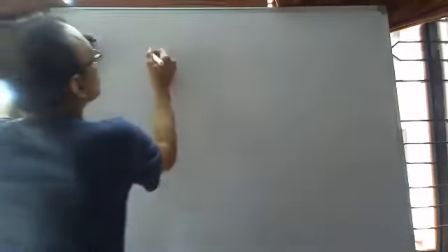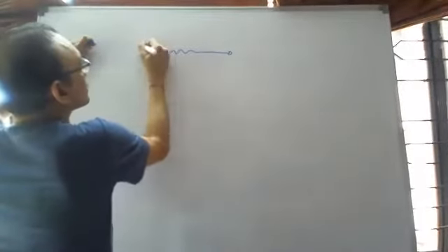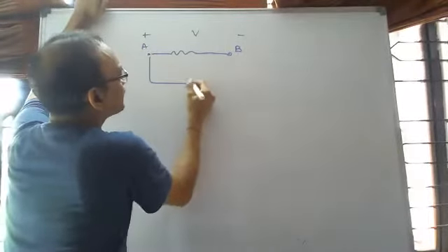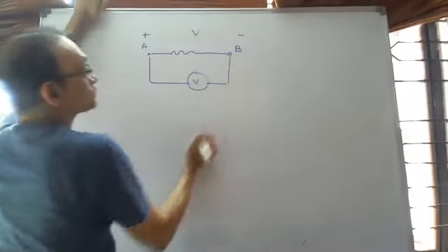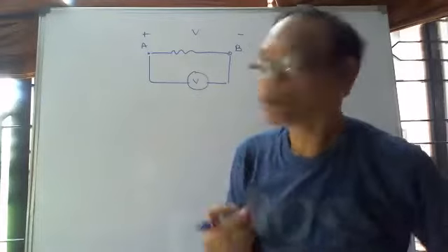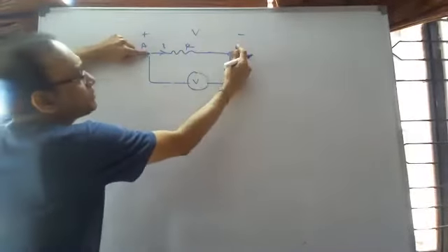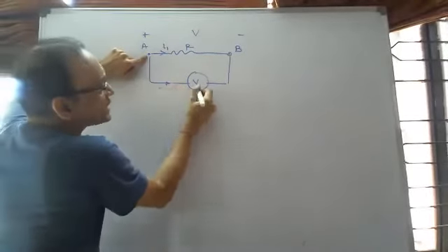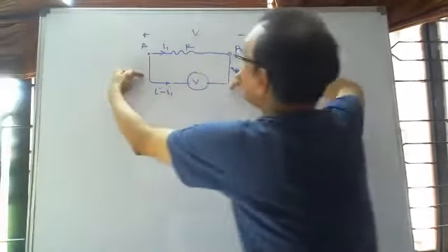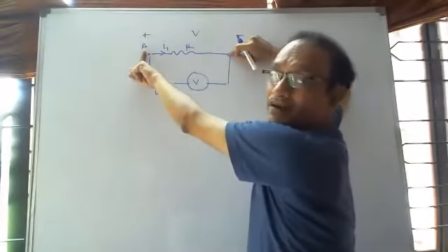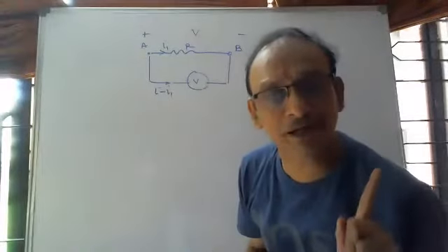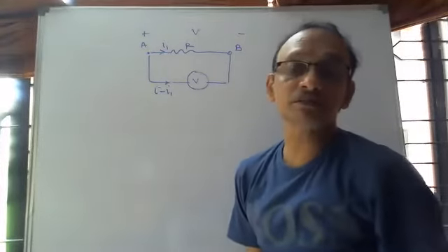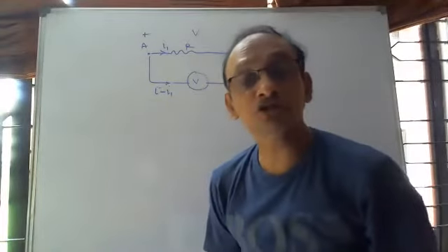कैसे error produced होता था? Suppose between these 2 points, I had to measure the potential drop. So what I did was, I connected these 2 ends in parallel to a voltmeter. But the voltmeter did have a resistance. इसका original drop क्या होता था? I into R होता था drop. पर जब voltmeter connect किया, then the current flowing through this resistance will become I1 से. बाकी current यहाँ से flow करेगा I minus I1. So which means now it's not going to measure I into R. It's now going to measure I1 into R. तो error produce होता था ना voltmeter में. So there was an issue with measuring potential differences in a voltmeter. It was subject to errors.